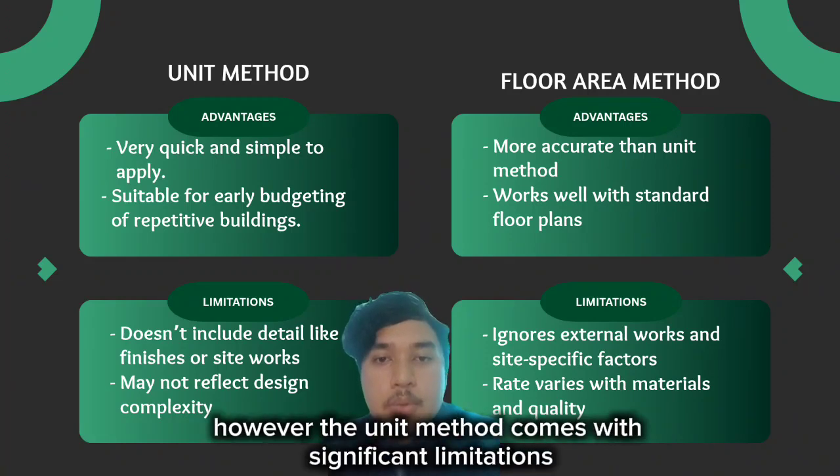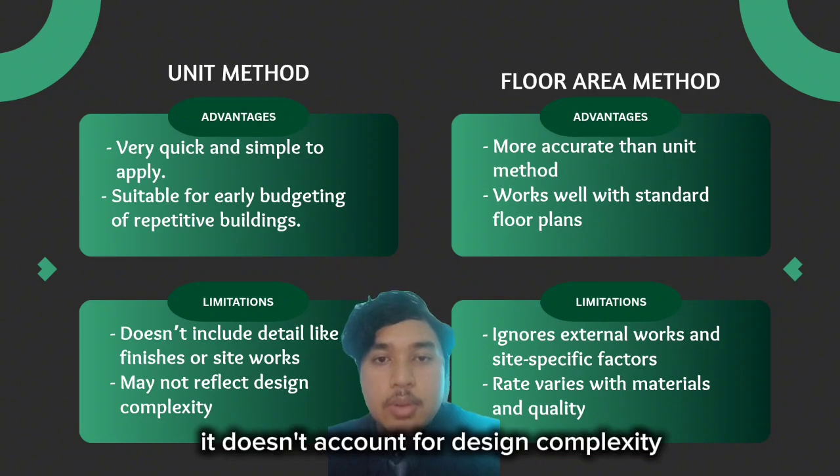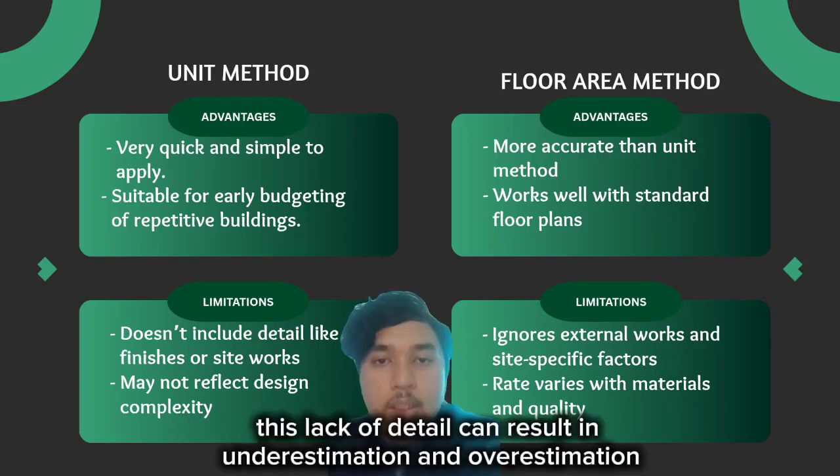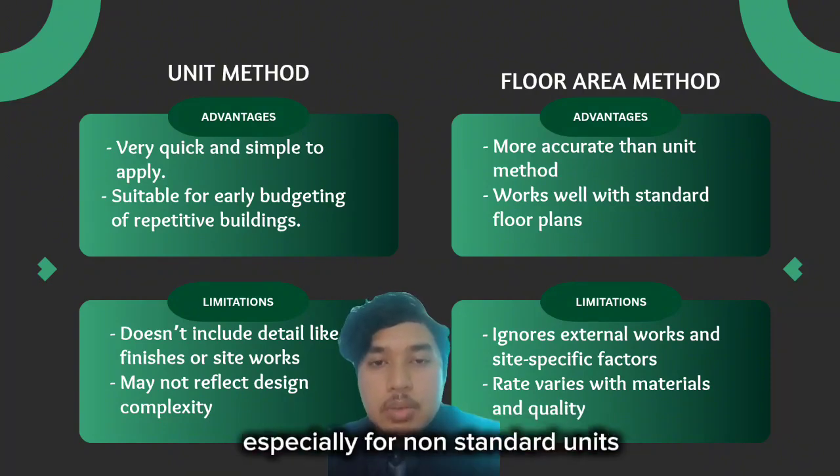However, the unit method comes with significant limitations. It doesn't account for design complexity, material quality, finishes, or external works like fencing and drainage. This lack of detail can result in underestimation or overestimation, especially for non-standard units.